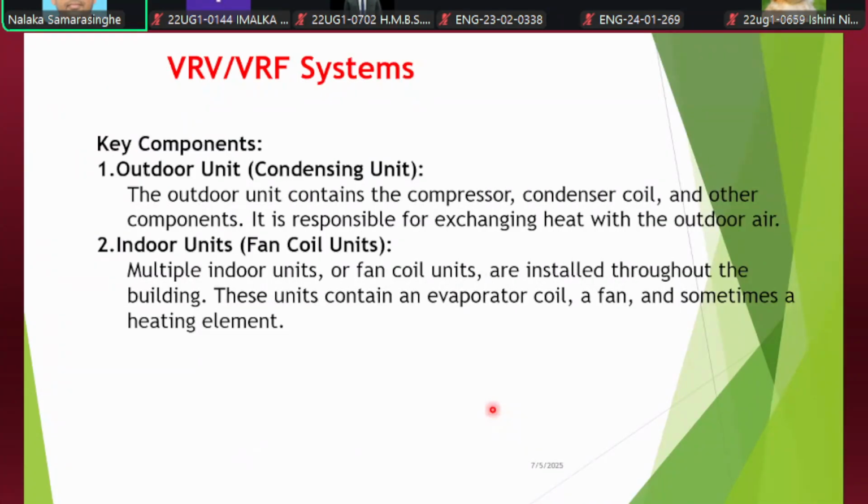Just to show you the key components of this VRV system, you have the outdoor unit, that's a condensing unit, and also we have multiple indoor units. Similar to the last one that I showed you, but here a number of fan coil units, or indoor units, can be used, and the temperature set points of those individual fan coil units can be changed according to your wish.